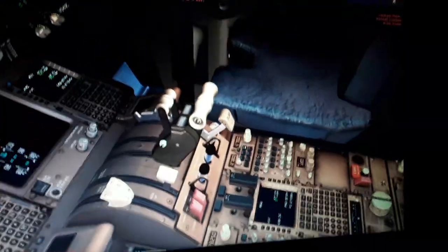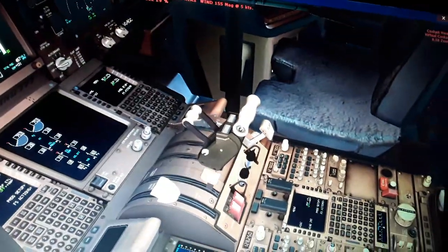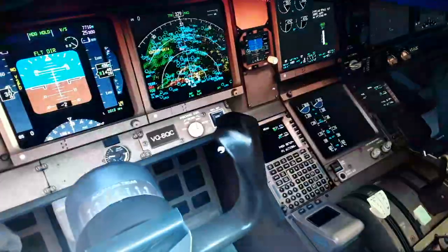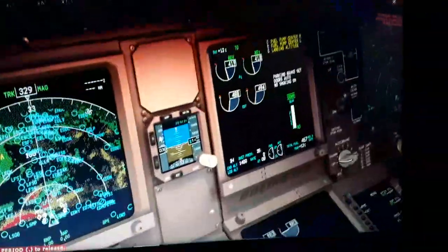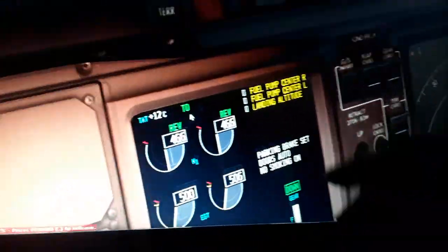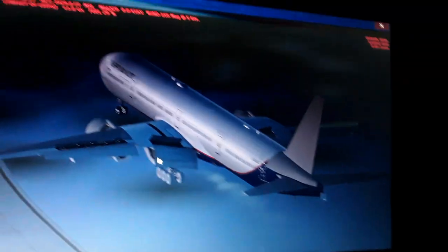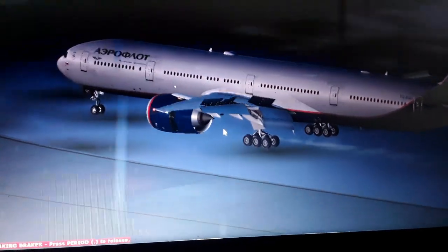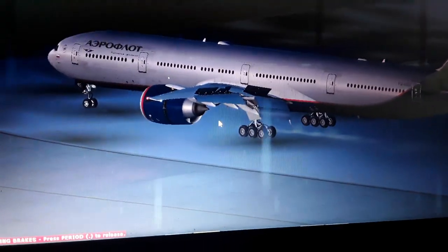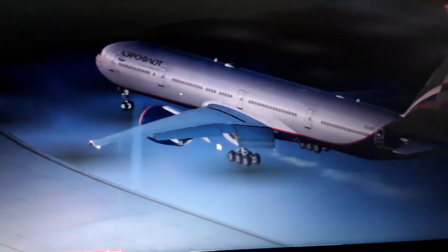So if you have the speed brakes extended and you move the thrust reverse, the speed brakes extend automatically. So you have the thrust reverse over here, and you see the thrust reversers in the blocker doors of the jet aircraft open. So you can slow down the aircraft in landing. You can extend them again.